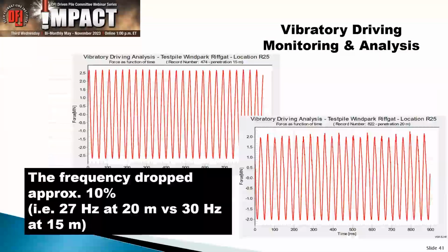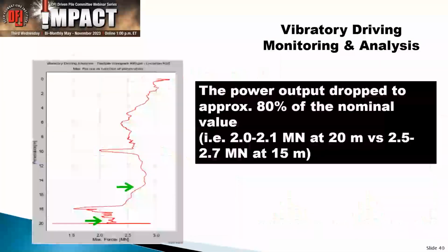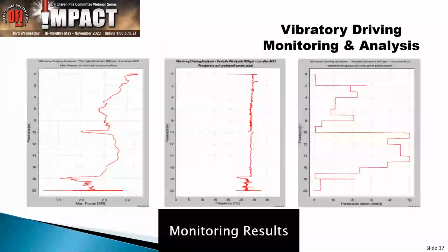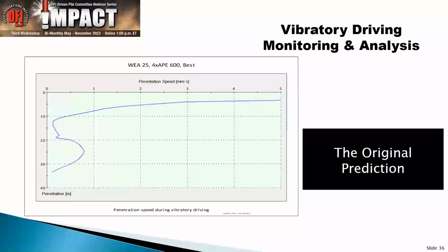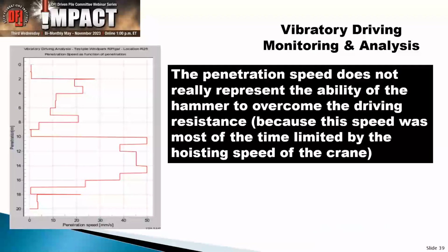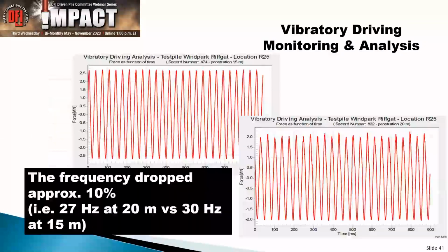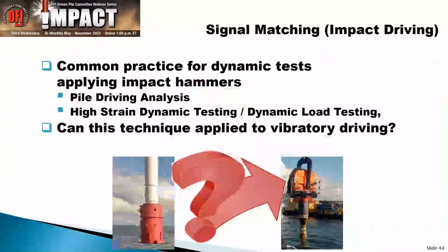Having said that, it's never as simple as one thing. If I have a higher frequency but a higher hook load, then the hook load can offset the impact of the higher frequency. So it's really a combination of everything, but all things equal, a higher frequency means that I have more capacity to drive things down into the ground.